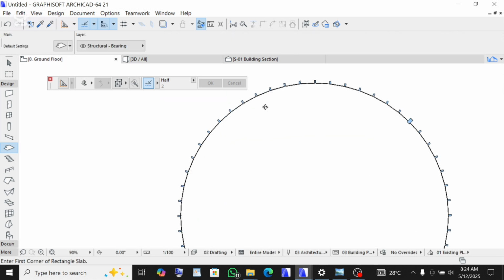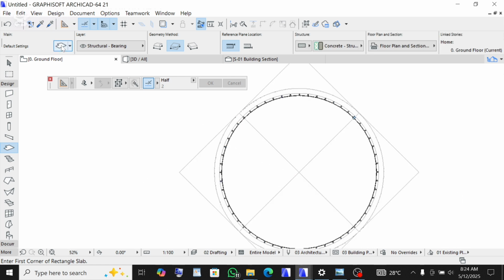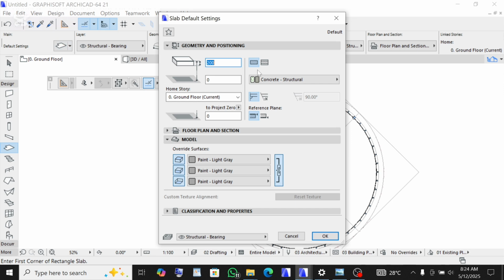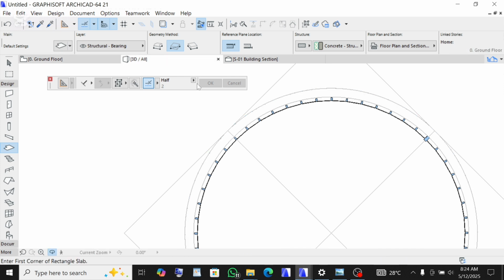Oh, sorry, we have not placed it. Let me go confirm if the settings are still there. So click on OK. Now we're going to place it around this part right here, not where the curtain wall is. So I'm going to place it at this first shape right here. So press spacebar on the keyboard and click on this shape, click on it and go to the 3D.